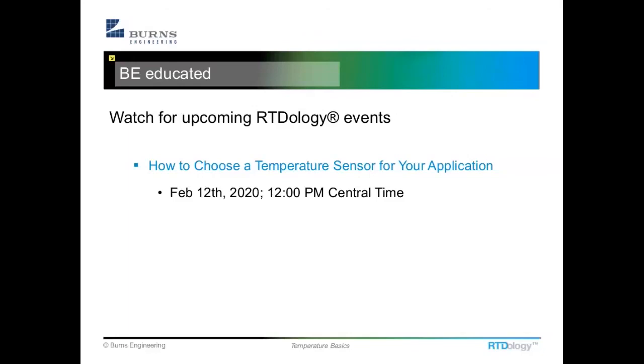I'm not 100% sure what that's referring to. I know there are cases where we can do an average temperature measurement with thermocouples by using what's called a swamping box, where we bring a bunch of thermocouples in. That can be done either in a serial connection or in parallel. But I'm not real familiar with doing that to measure small temperature differences.